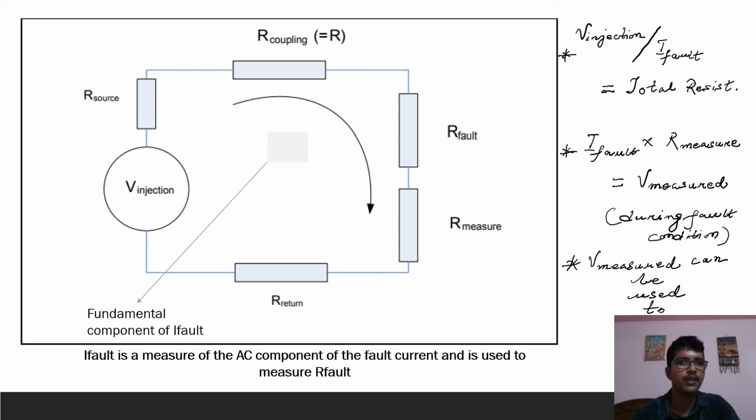For second rotor earth fault analysis, it becomes very different. In fact, we need not wait for a second rotor earth fault to develop. The first rotor earth fault automatically will ensure the tripping signal reaches the proper target.